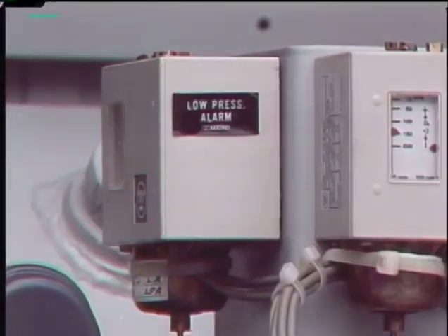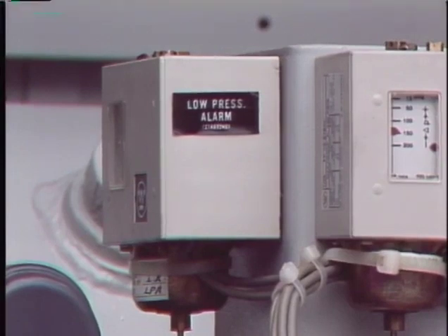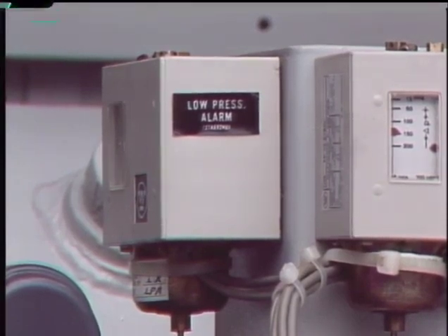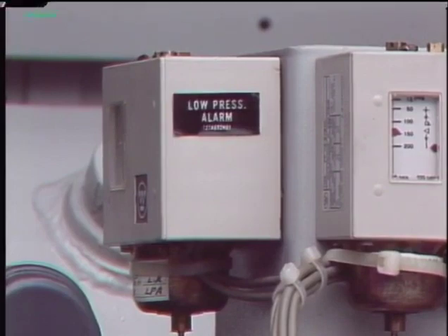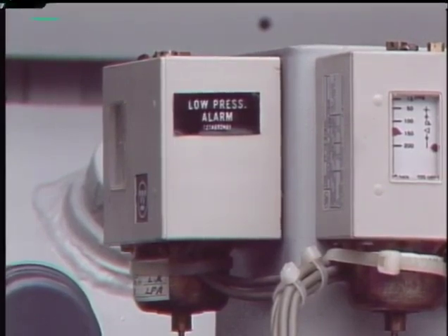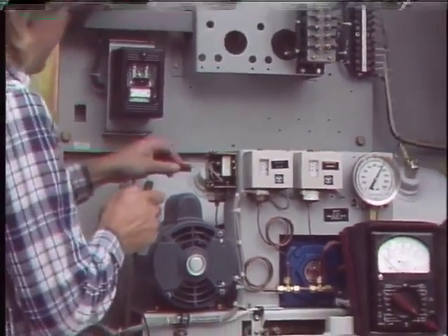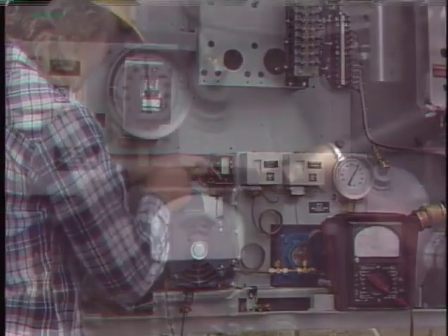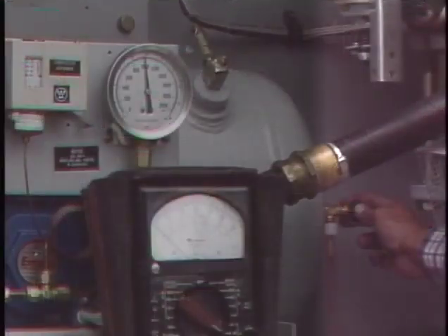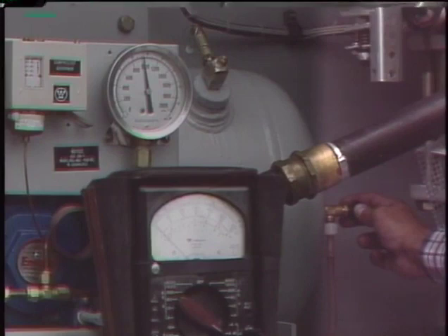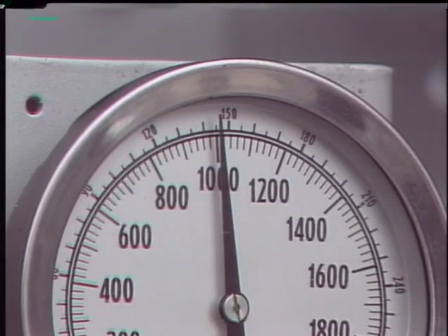The low-pressure alarm switch gives a warning that system pressure is getting low. If the pressure falls too low, the breaker may not operate when needed. To check the setting of the alarm switch, de-energize the compressor so that it won't operate. Then a device such as a volt-ohm-meter can be connected to the switch terminals and set to the appropriate scales. Slowly bleed the system pressure until the meter indicates that the low-pressure alarm switch has operated. When the switch operates, note the pressure and, if necessary, readjust or replace the switch.